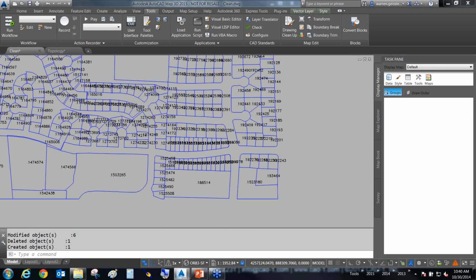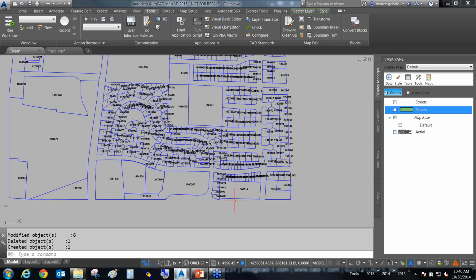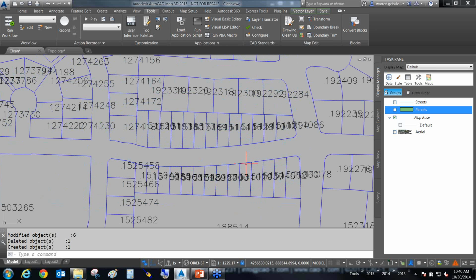Now, I'm doing this very quickly, and I'm tweaking around with some of the numbers, and it's not like you're going to do this automatically. This does require training in a conscious methodology of cleaning up your drawing, but I do want to show you what the program's capable of doing. It can do all of these things for all of your AutoCAD entities. Duplicates, the 0 length objects, where objects cross. It went ahead and snapped this polyline up here where the objects crossed.